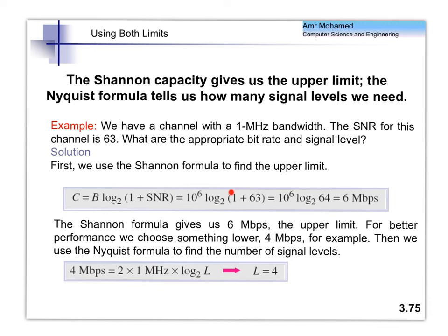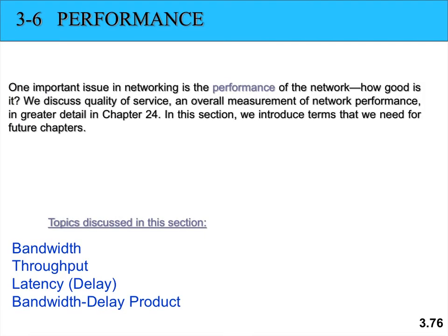And if we increase it more than 4, you may not be able to get it through this channel because the theoretical limit is 6. So if you increase it above this, actually maybe 4 megabits per second might also not be achievable over this channel, as we will see later. So there's a big difference between the theoretical bandwidth, or the limit of the channel, and the throughput, or the actual data rate that you can get.